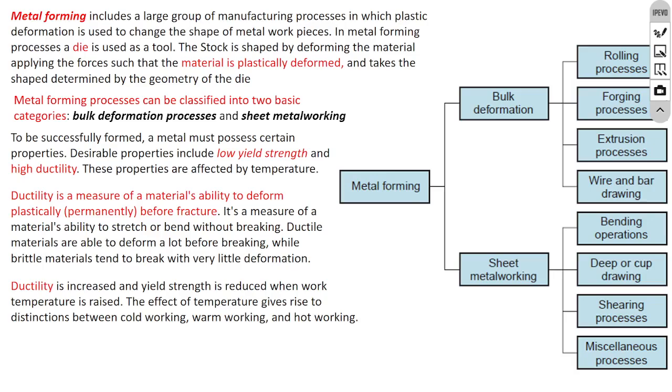That is the reason why in metal forming it is quite common to increase the temperature of the material before the deformation stage, to be able to decrease the magnitude of the forces that are needed to deform the body. We put the stock into a furnace, we heat it up. At a higher temperature, we can shape the object much more easily.